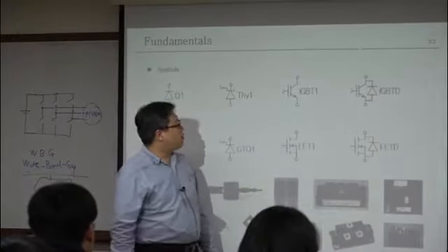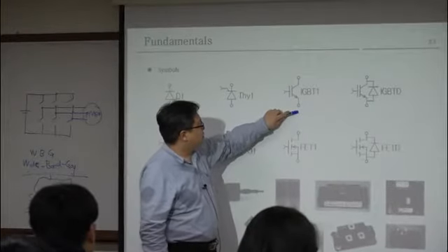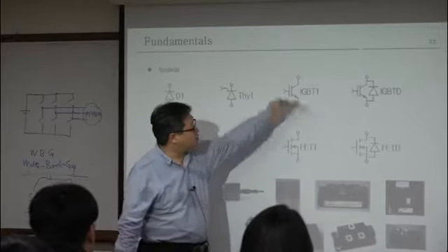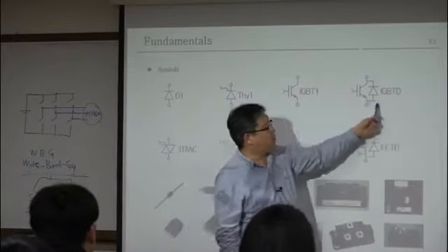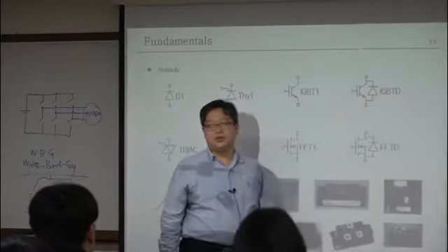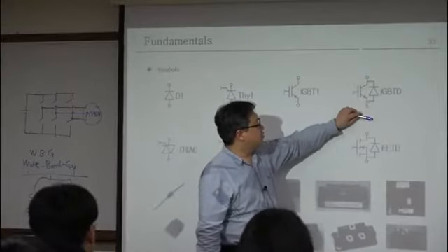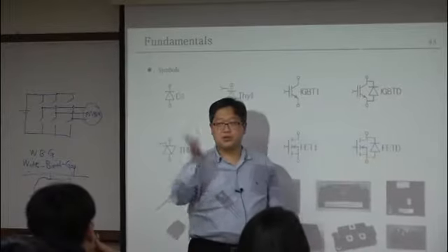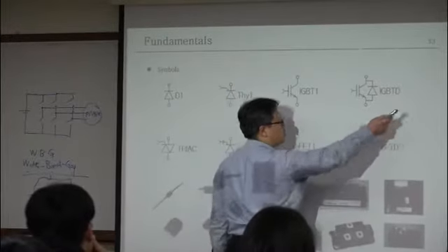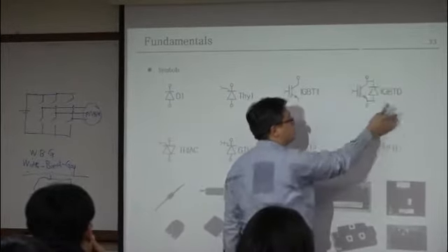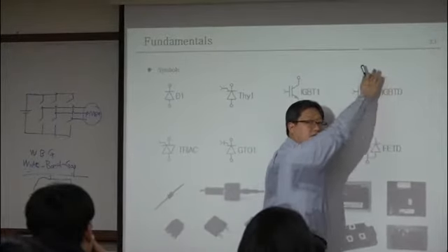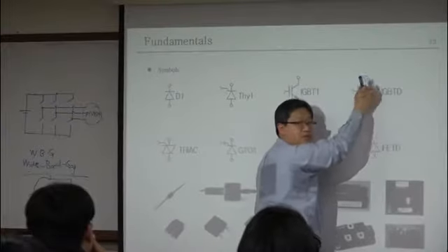So to flow the current from the emitter to the collector, you should have the diode. Since you have the diode, can you cut off the current here? No, because as long as you get the current like this, even if you turn off the gate, you can flow the current, right? Because this is the diode.